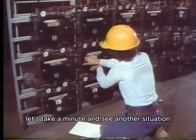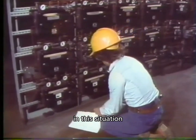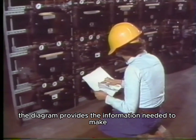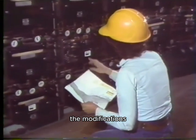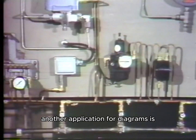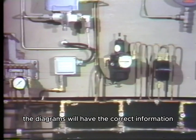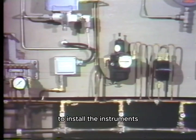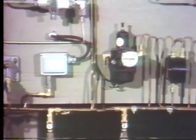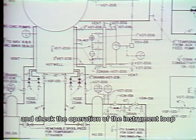Let's take a minute and see another situation in which a technician uses a system diagram. In this situation, the technician is modifying an existing instrument control system. The diagram provides the information needed to make the modifications and to install the instruments correctly. Another application for diagrams is when a new panel for a control system is being installed. The diagrams will have the correct information to install the instruments and make the proper connections. After completing the connections, the diagram also contains the information a technician needs to calibrate and check the operation of the instrument loop.